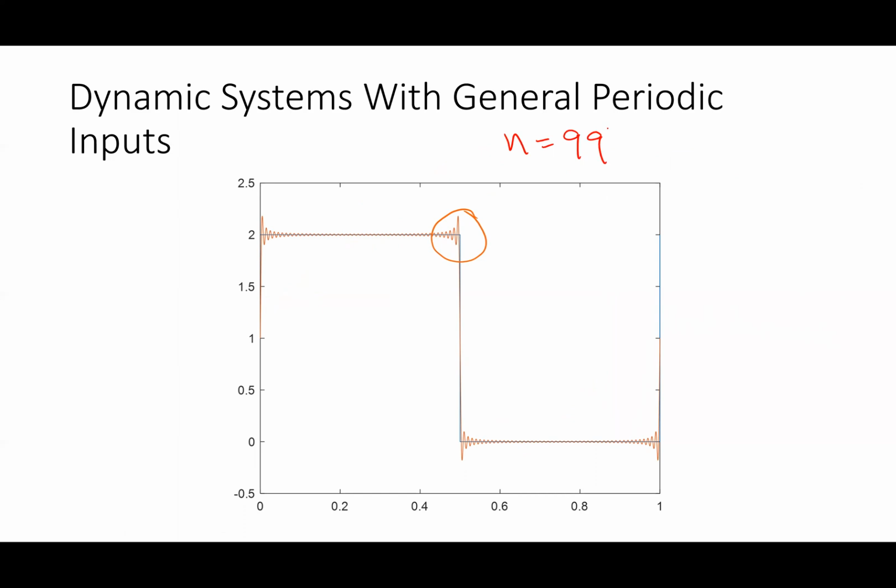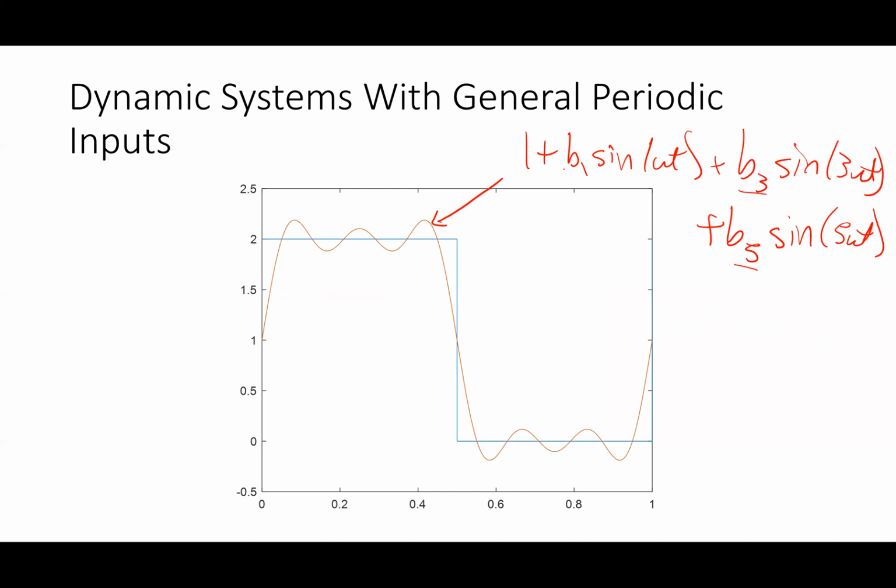Now I can see that summation is starting to look pretty close. But what's important is the amplitudes here have to be just right to make that work. The thing we've got to do is figure out how we get those amplitudes. There's a whole mathematical procedure for doing that. You guys use oscilloscopes in the lab, but the other tool, I don't think you use in the lab, is a spectrum analyzer. Basically, I take a waveform like that square wave and it tells me the harmonics that are there. There's a lot of tools that'll tell you that kind of thing.